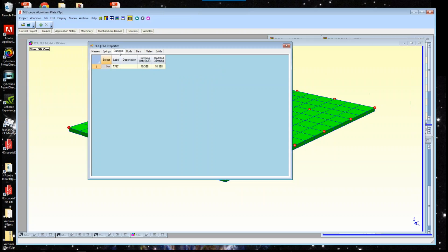Those are nice and simple. Point masses, springs between 2 points, and then we can have torsional springs and springs in specific directions. Same with dampers. SDM handles dampers very well. I can even add dampers to my FEA model, and we use the SDM algorithm along with an FEA solver to come up with the damped modes. That's something that's unique to us. Most FEA codes don't deal with damping very easily, at least.